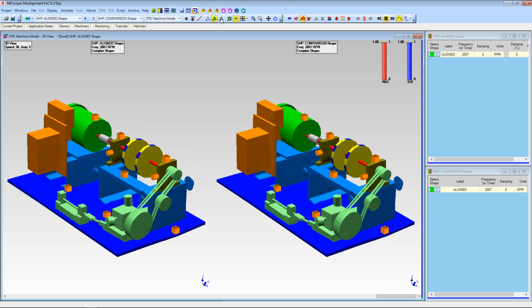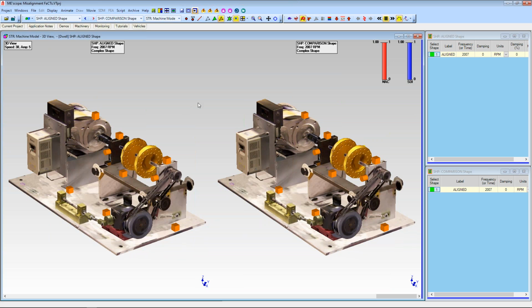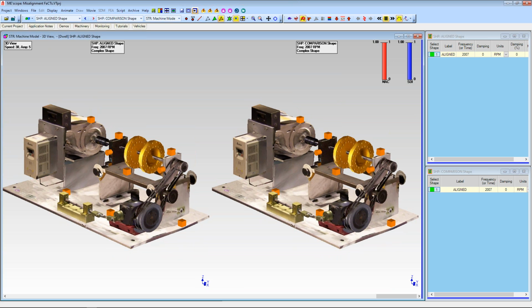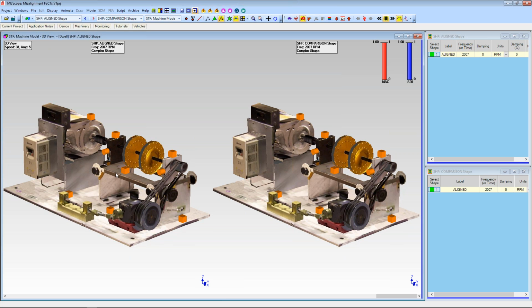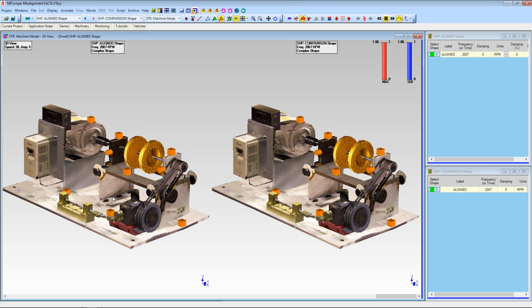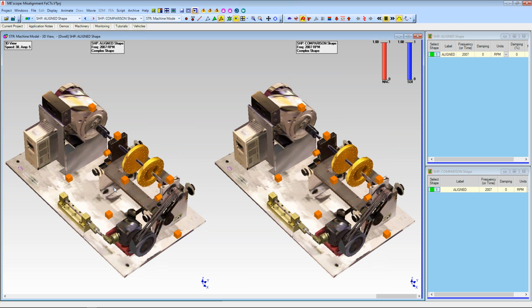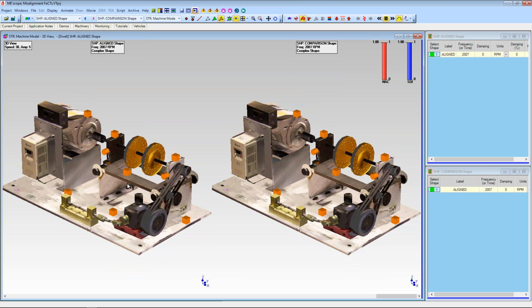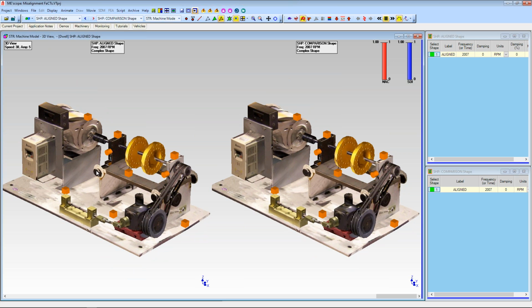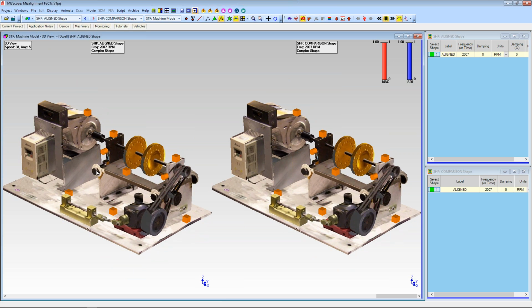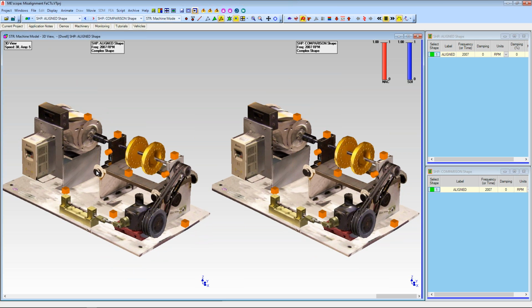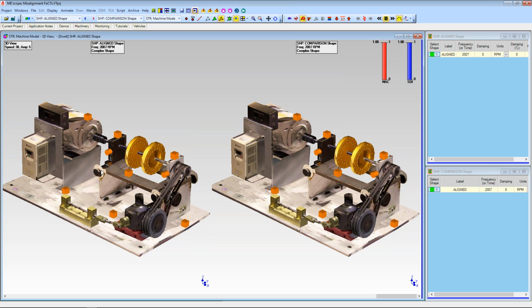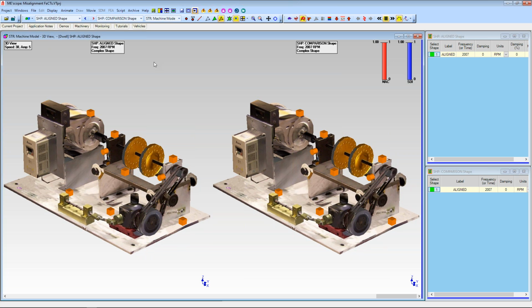If I go back to the photo model here, you can see how we did that. There's a couple of little screws here that actually move the bearing blocks and some of the framework underneath the bearing blocks, so that we can crank in with these little screws here both parallel misalignment and angular misalignment. So that was done, and then data was taken, and we have that data recorded here in MEScope as a set of ODSs.